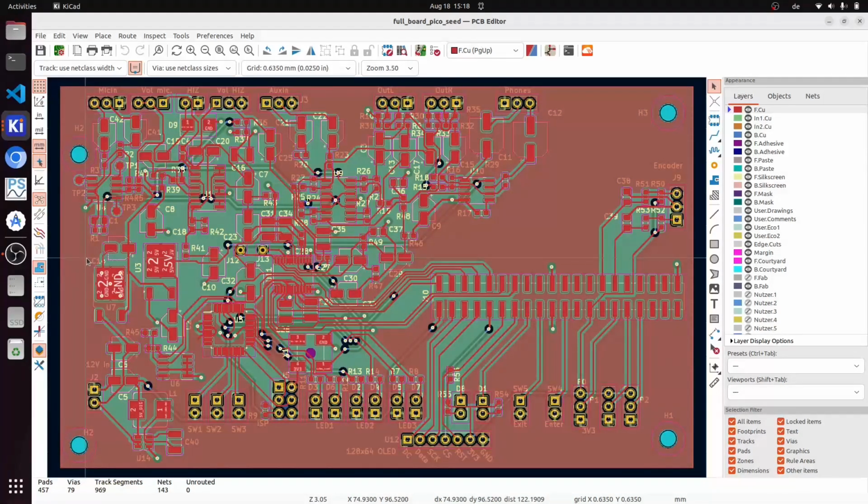One basic principle I applied, that I tried to physically split the analog and digital part. So analog is everything on the top part. Here you see the microphone input with one of the op amps, the NE5534, and the other op amps built around the analog part. It's all on top, meaning above this virtual line we have here.